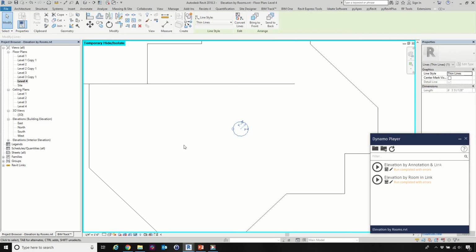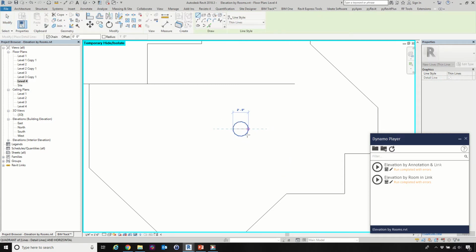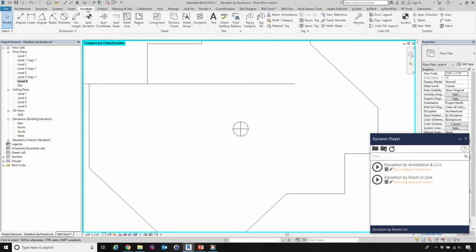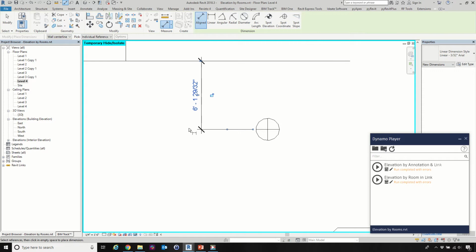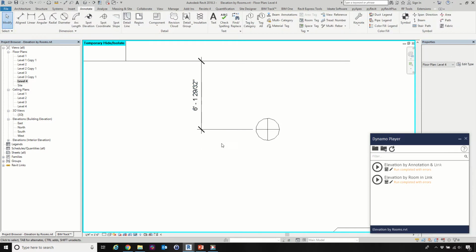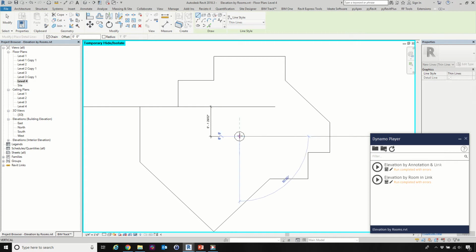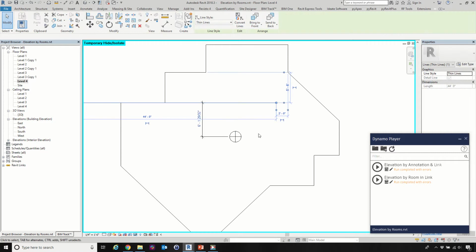And now we measure the distance from the room center to this curve. Because we extend the curve really long, we're getting the perpendicular distance in this case. If we're using the old curve, we may be getting this distance because that's the shortest distance. Now we extend that very long, we're getting this distance. And now we have the point and the extended curve.